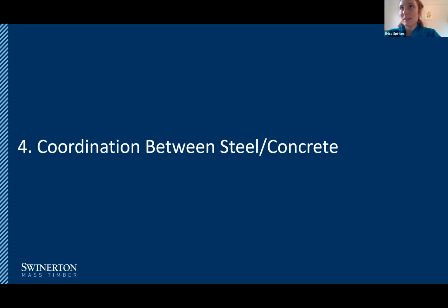That system is utilized in applications where we've got longer spans. It just increases the spanning capability of the CLT panel. It does increase the amount of wood fiber in the system, so I'm not sure it's necessarily the most structurally efficient, but there are definitely applications. And in residential, it actually could work quite well with just distribution of services through the units, from the corridor to the units. So yeah, I'm really interested. I'm curious about the system. We haven't built one like that though.